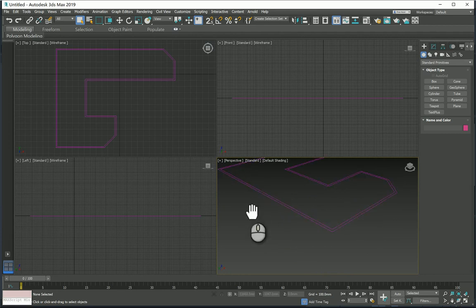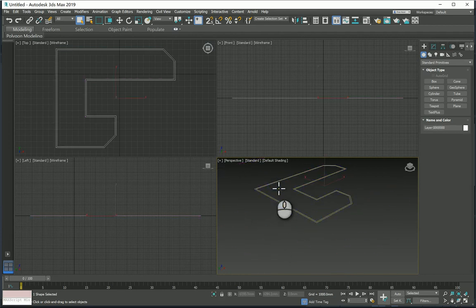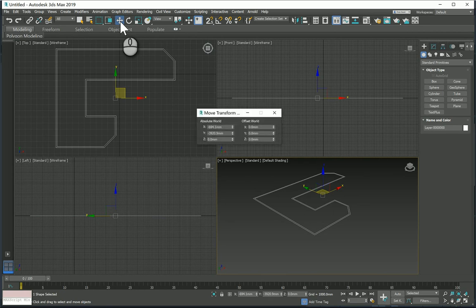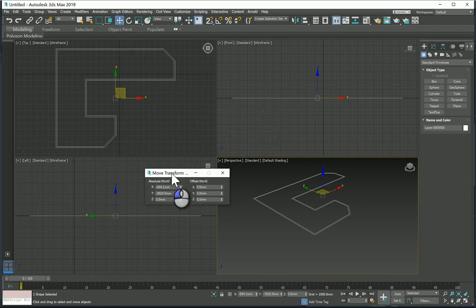And now that's the benefit of having the magenta or the ugly color, just to distinguish it. Now there is nothing to be distinguished from, but later on when it's accumulated too many objects, you're gonna need something to distinguish your work. Right click the new file from those you actually sent. Right click on the move. Now the Z value, as we said, rule number 1, exterior wall, always follows the lower level.